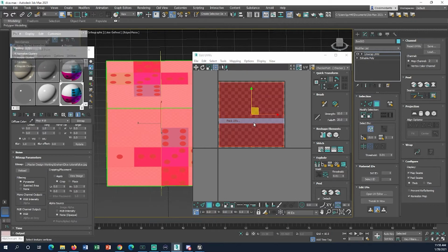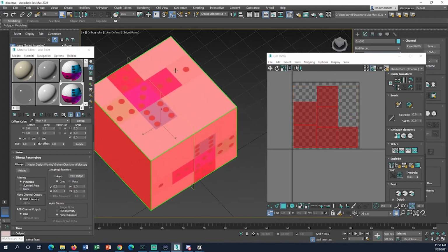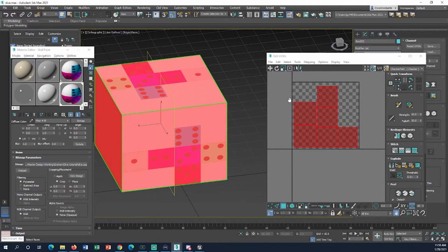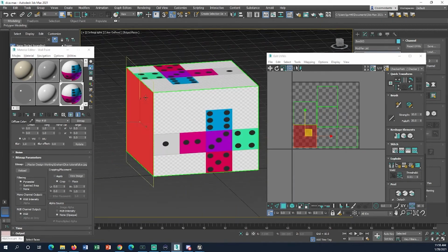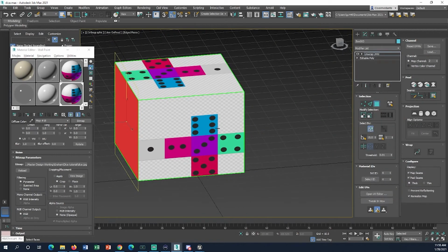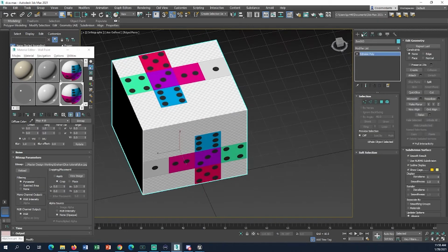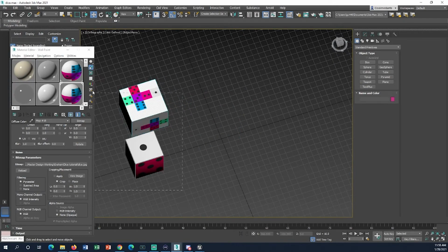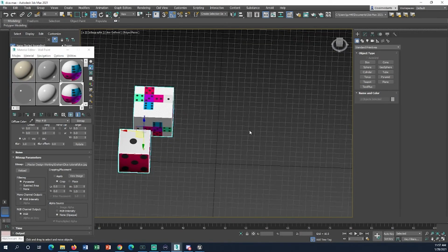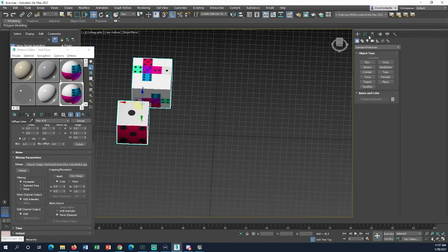But in this circumstance, I can pack the UVs just like this. As you can see, we're still utilizing the full amount of pixels for the planes over here, but then we packed it in nice and tight over here. So this will still work for the light mapping in Unreal Engine, and I can get higher resolution textures, but all the faces will be the same. Depending on your purpose, there'll be lots of different uses for each of those, and either one is acceptable, but you just have to make sure you don't overlap your UVs in the first channel so you don't cause problems with the light mapping.